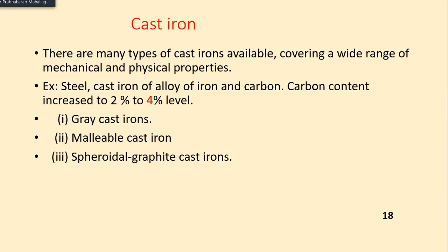But anyway, we study the engine. So in the engine, where do you get this cast iron? That is available in the engine block, right? In the engine block, you get cast iron. Cast iron can withstand high pressure, but it can't stand any blow, right? You may have a crack.